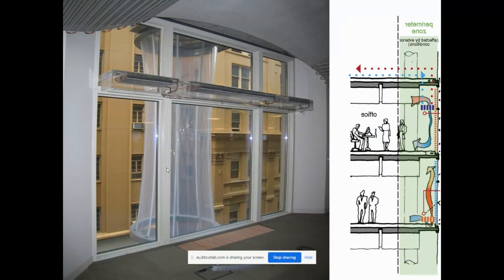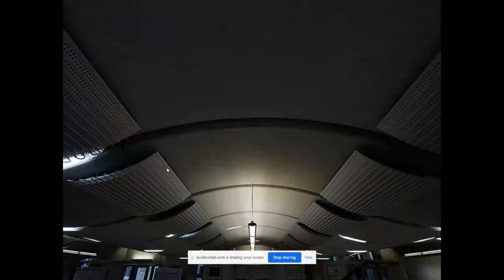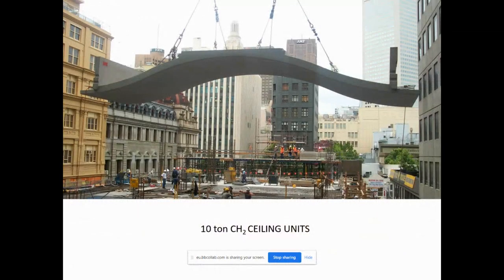Okay, so there's a lot of physiology in this. We're thinking of human physiology. The window has grills at the bottom letting in warm air for the winter, and always in front of the glass. And then the ceiling is cooled at night by automatic windows that open and just let the outside air in. And because of the diurnal swing, we're able to use that day and night temperature to cool down the concrete. I'll show you some more maths on that.